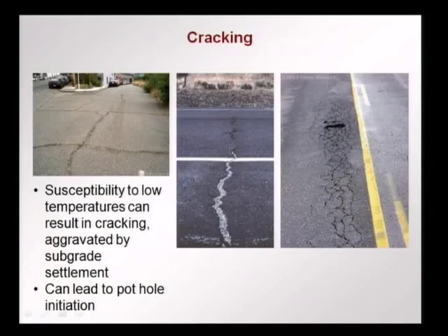So, when there is, say, the subgrade slowly settling along this section, if the viscosity is so high or the stability is so good that it cannot adapt to this subsidence, then a crack develops, because under the asphalt concrete there is no support. So, a crack can develop, and this can have pattern type cracking or single cracks. You can also have, at low temperatures and poor mix design, this pattern type cracking.